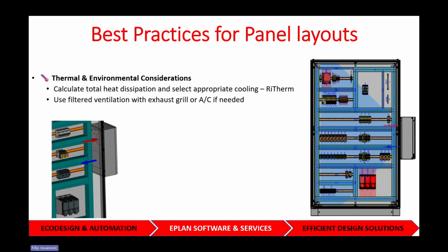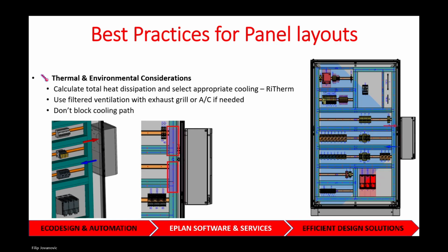And since you most likely will use a fan or an AC, it's also a good idea to use an exhaust grill or an outlet filter for those fans, just to clean out the air. You also don't want to block your cooling path. So in ProPanel, ProPanel makes it super easy for you to visually see where your airflow is going to be, or if anything's blocking it.